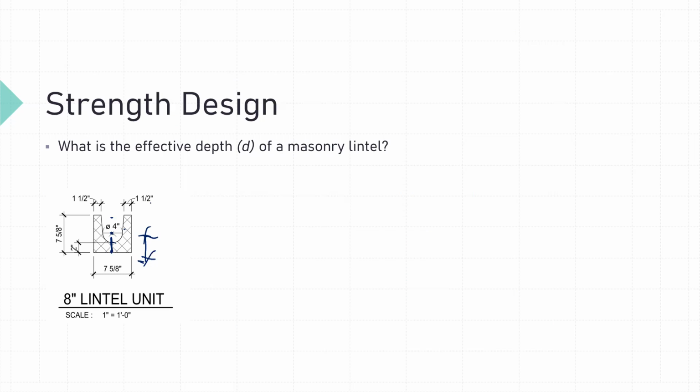So the other way that we make lintels is using a bond beam unit. So it's going to look like a standard unit. And when they make that unit, they are going to put these notches in it so that a mason in the field can take a hammer and knock out the crosswebs. So then we can put our longitudinal reinforcements in here. And so usually with a knockout type bond beam unit, the lowest we can get the reinforcement in that unit is going to be at about the height of our unit divided by 2. And so if we're using a split face type unit, burnished unit, typically the lowest we're going to be able to get those longitudinal bars will be the height of that unit divided by 2.